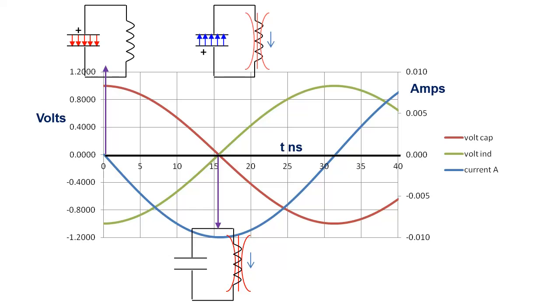Therefore, at an instant immediately after the previous instant of time, the capacitor develops a small negative voltage, and a weak electric field, as shown by the blue color. Thus we see how the capacitor voltage changes sign. The magnetic energy in the inductor keeps charging the capacitor till inductor current becomes 0, and maximum voltage is reached in capacitor with strong electric field, shown by the red color, but obviously, with a reversed polarity. After that, the process repeats itself.